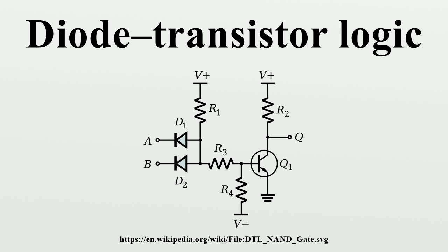In 1964, James R. Beard filed a patent for the Schottky transistor. In his patent, the Schottky diode prevented the transistor from saturating by minimizing the forward bias on the collector-base transistor junction, thus reducing the minority carrier injection to a negligible amount. The diode could also be integrated on the same die.